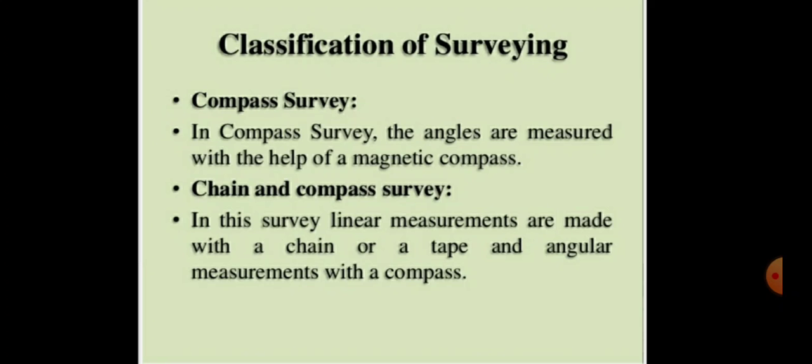And next is chain and compass survey. In this, both the chain and compass are used. The chain will be used for the linear measurements and the compass will be used for the angular measurements.